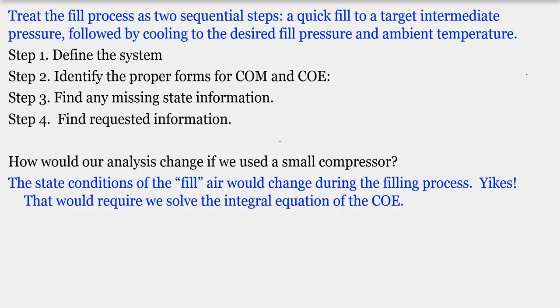Well, as we saw before, this transient analysis is pretty complex when we have steady conditions from our filled chamber. If they're unsteady, the analysis is even more complicated. So let's take a look at the specifics. So if we have our conservation of mass equation, recall before we had the change in the mass in the control volume from the initial to the final state was given by this expression for the mass flow rate into the system here. So what we need to know, again, is how does the mass flow rate vary as a function of time? And for this, you'd say, well, let's take the draining tank example.